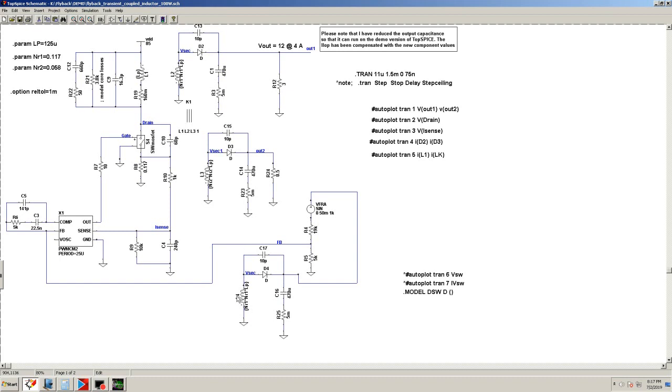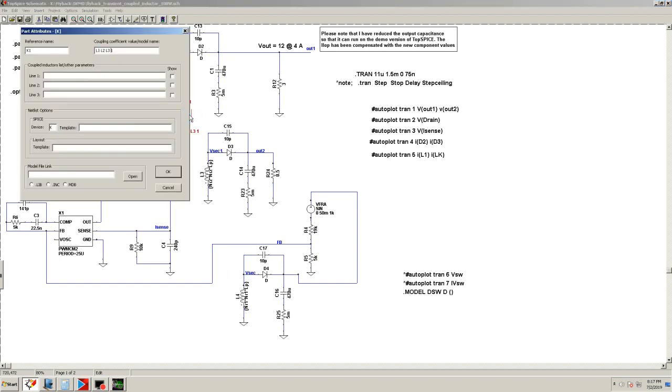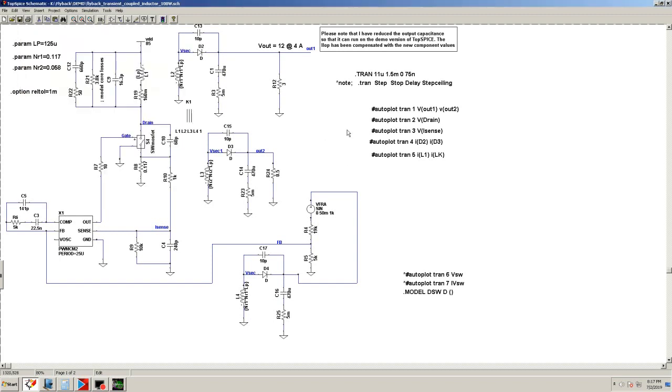And now let's couple it. So now this is L4. So all I have to do is go to K1, type in L4, and that should couple it. Okay. So now this winding is a third winding, and you can close on this. But this could be referenced to the primary, while these are referenced to the secondary. Okay, doesn't make sense here, but in the next lecture I'll split up the grounds and maybe even do an opto so you can see the difference.